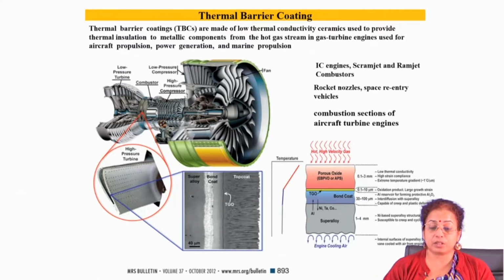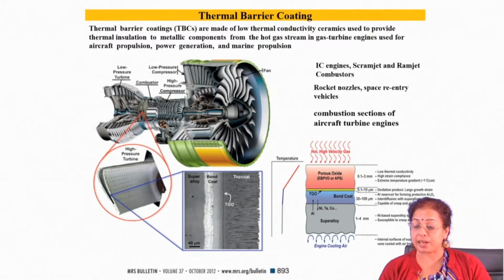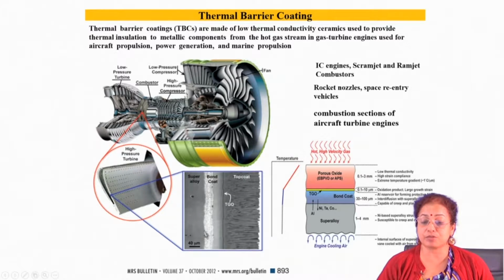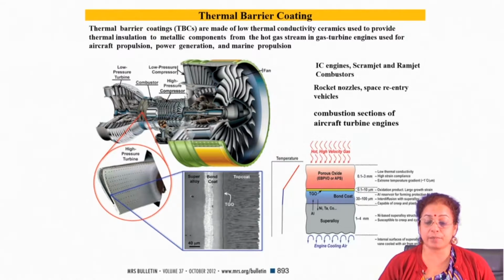That coating is developed onto the surface of the superalloy, and before that you apply a very thin bond coating made of CoNiCrAlY, which offers the high temperature oxidation resistance property, and the oxide based ceramic offers the thermal barrier property, or acts as an insulating barrier for reducing the effective operating temperature of the substrate. Usually this top coating is applied by electron beam physical vapor deposition technique or by air plasma spraying technique. But each and every technique has its own advantages and disadvantages.